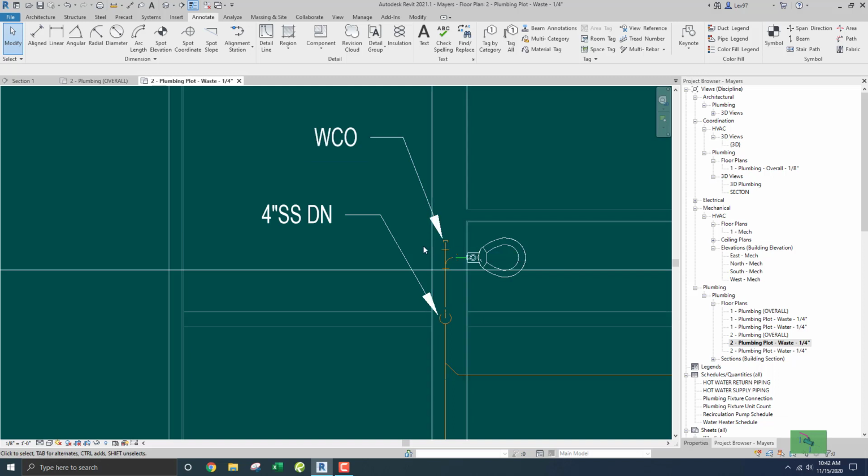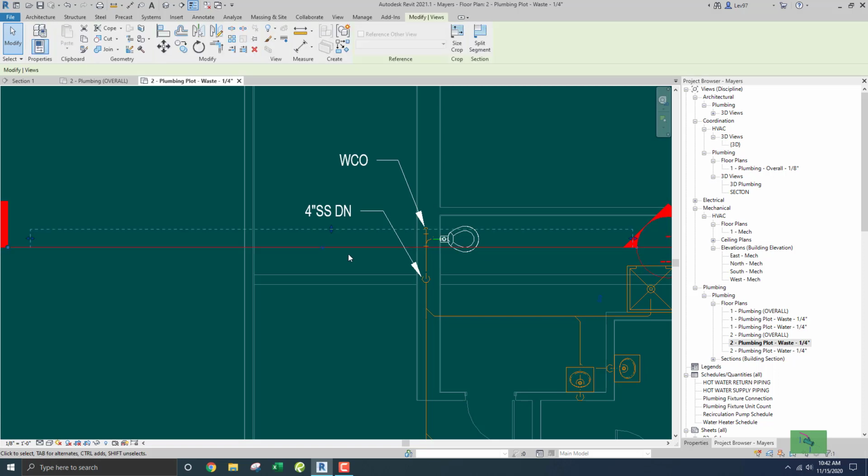Or you can go down in the basement or in the attic or in the ceiling of the first floor and create your clean out. You can do it like that, and it has to be 18 inches if it's more than 2 inches from any kind of obstruction, or it can be 12 inches if there's an obstruction between, like a 2x4 or a beam or whatever. So let's take a look at that.